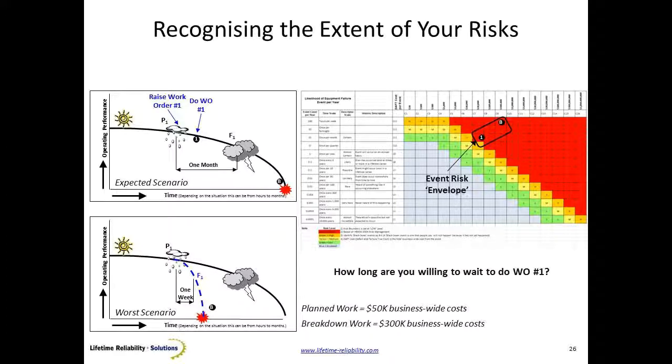I'm then going to ask, in this case here, our pump has got a problem. The curve is beginning to drop away. So we've raised a work order to repair this pump. Vibration or temperature or something's triggered a recognition of the degradation happening. In this case here, I've given myself a week.